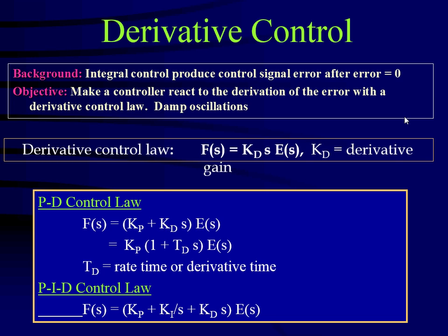So you see each one of the controllers has a plus and also has a negative. The proportional control is very fast, but you end up with a steady state error. The integral control gets rid of the error but makes the system oscillate. And the derivative control puts damping into the system and therefore damps the oscillations in this case.